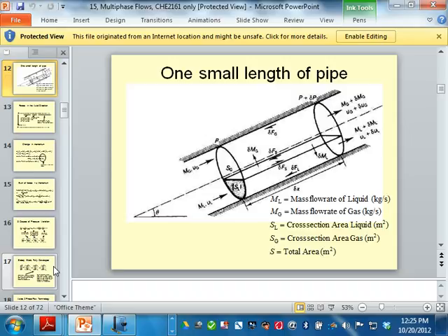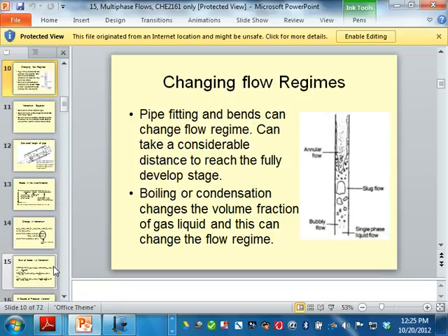The third one is a bit more confusing because we didn't see this before. There's an acceleration term. Previously, we said steady state and there was no acceleration, in our Bernoulli equation, energy equation. In this case, even a steady state will have acceleration. Why? Let's go back to the boiler tubes, where liquid becomes gas.